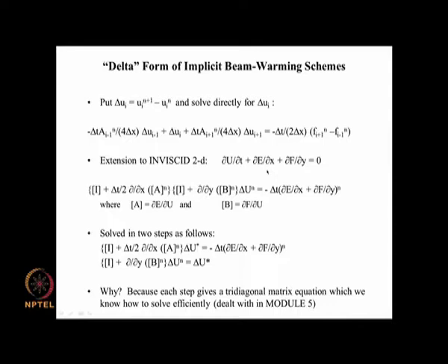So, you have zeros in between some diagonals, and that is a typical pentadiagonal form that we get when we discretize a 2-dimensional equation. When you have a pentadiagonal matrix, the tridiagonal matrix algorithm cannot be used directly. But by first doing the x derivatives, because in this equation the right hand side is evaluated at the nth time step and is all known, and you have ∂/∂x of Δu*, this involves only i-1, i and i+1, so that becomes a tridiagonal matrix equation.